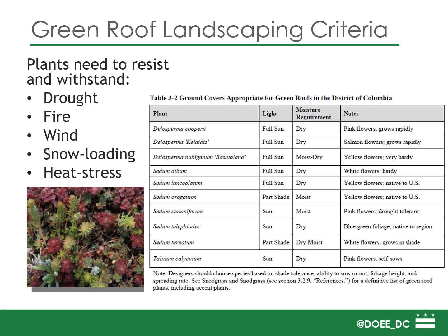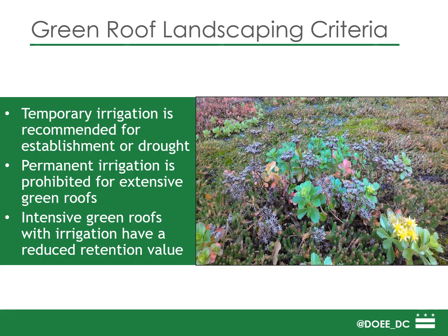You can put higher, more sensitive plants in a green roof, but it generally requires deeper media depth, and the watering of these landscape elements is a consideration as well, which I'll get into in a moment. So for the extensive green roof and the intensive green roof, you have to have some sort of temporary irrigation, right?